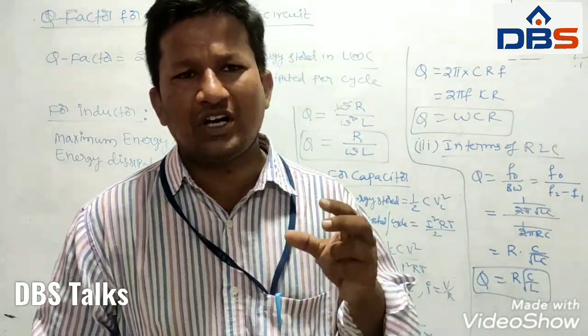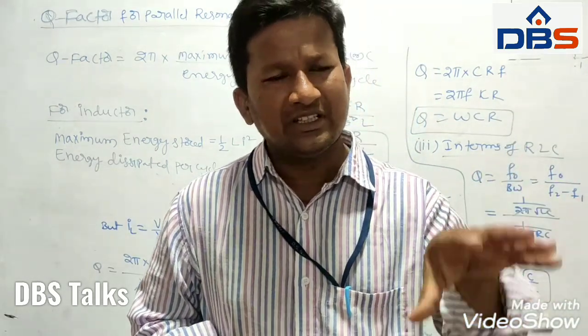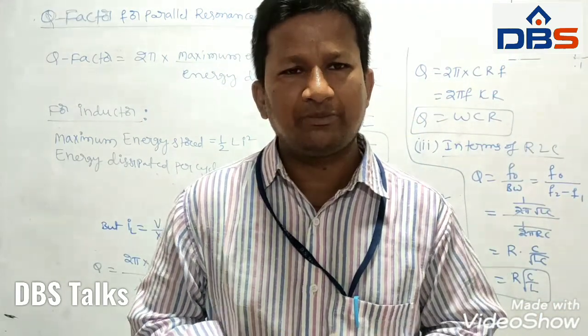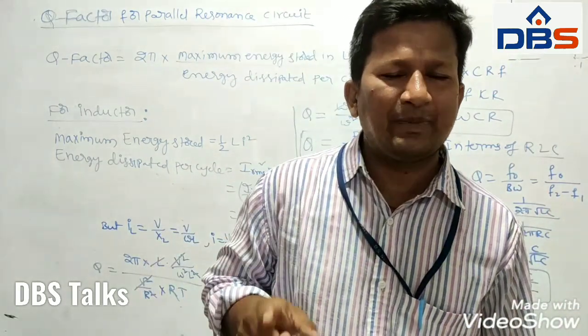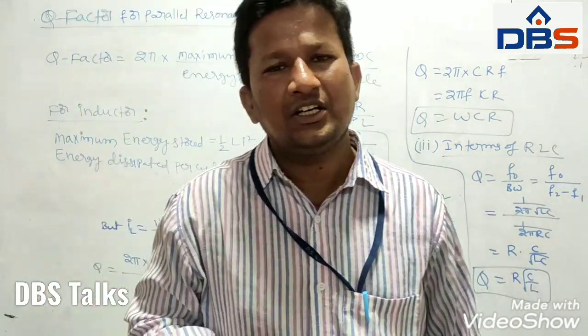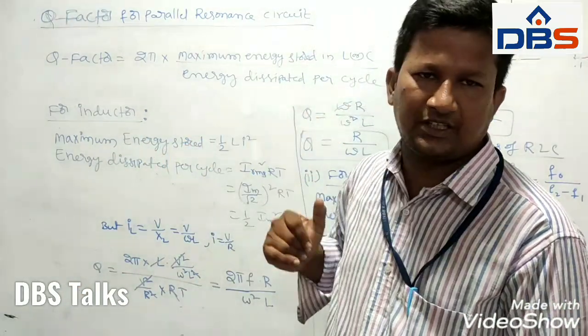You already know what quality means. Quality of an inductor or capacitor in a given circuit means the performance of the inductor or capacitor for a particular circuit. Quality factor is defined as 2 pi times the maximum energy stored in the inductor or capacitor, divided by the energy dissipated per cycle in the resistor.